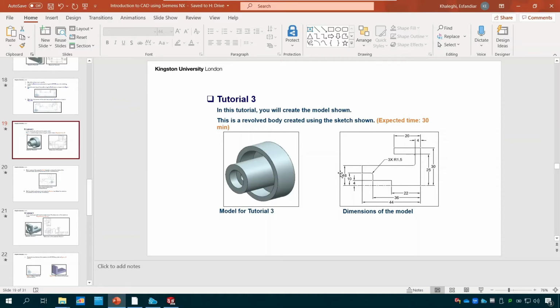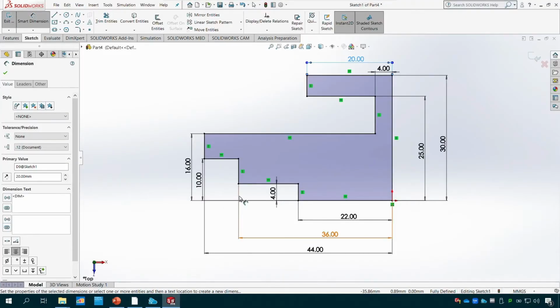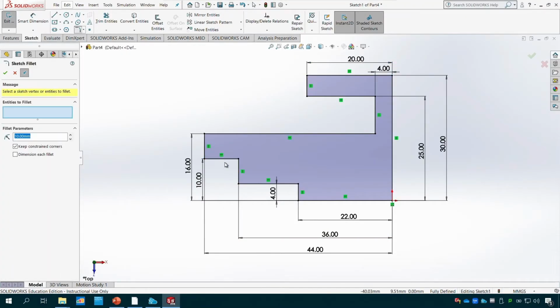So what I just need to add is just a fillet of 1.5, and I have 3 of it, which is basically 1, 2, and 3, 1.5. So I do have a fillet in here between those two. And let me see whether you pick it up correctly, this one and that one. Do you see the error that I get because 10mm is bigger than this one? Of course. And so let me put 1.5 and then these two.